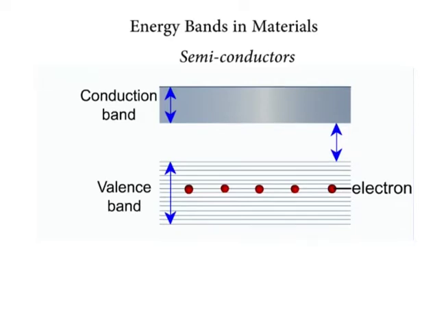At high temperature, electrons excited by heat can gain enough energy to jump from the valence band to the conduction band. When this happens, the electrons leave holes in the valence band which behave like positive charge carriers and can also move freely. When a potential difference is connected to the semiconductor, the holes and the electrons move in opposite directions and are called the charge carriers.